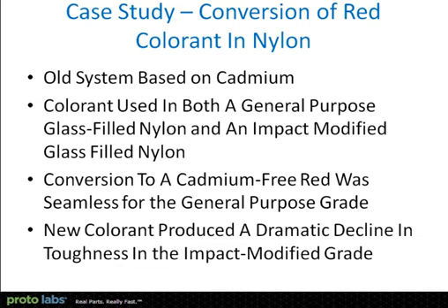Here is a case study of something I was personally involved in: converting a red colorant for nylon from a cadmium-based system to a cadmium-free system. Now, we had done this conversion in polycarbonate. It was very straightforward. We did it on the first pass. There were no sacrifices in performance, no sacrifices in processability, and everybody was happy. We did the same thing in a general purpose glass-filled nylon, and that conversion was seamless.